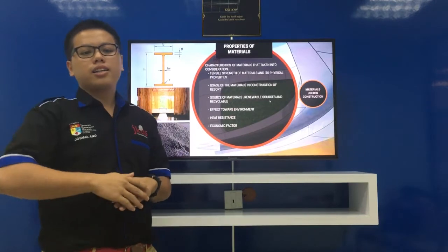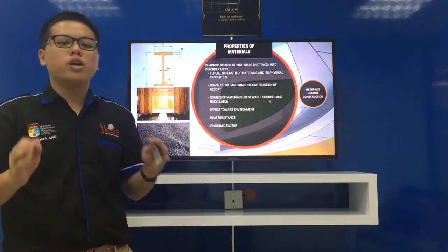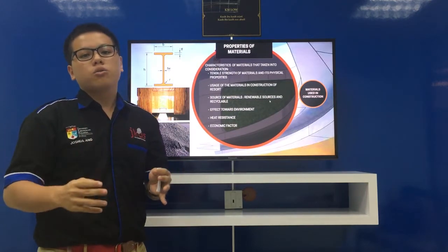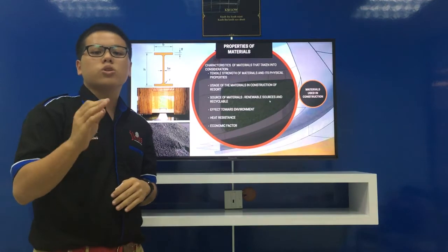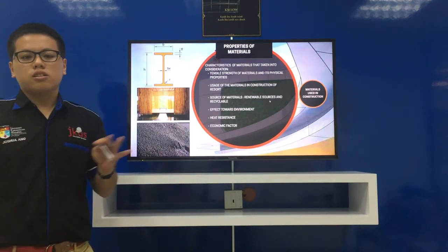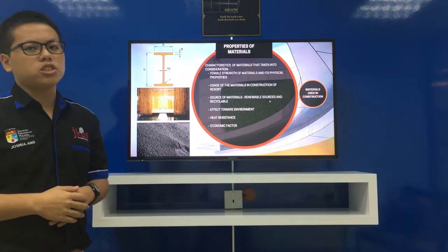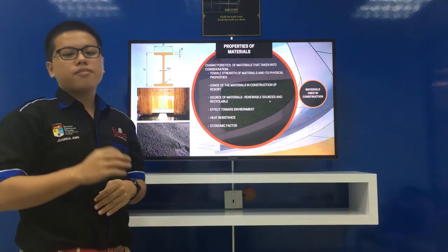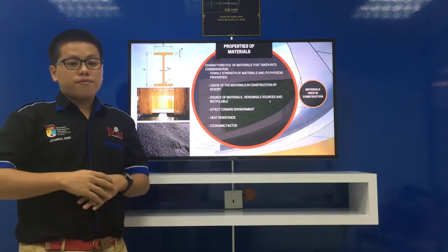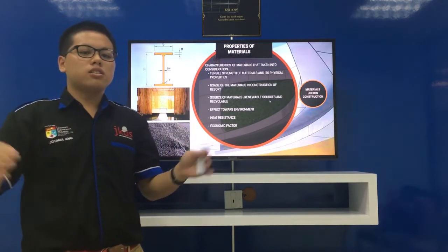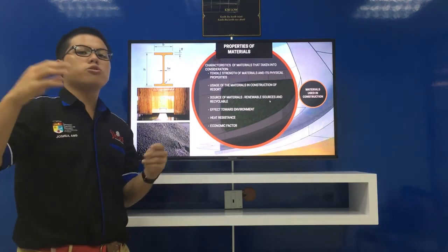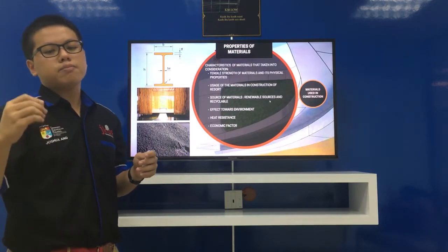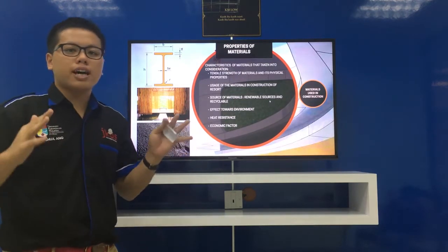Okay, in a beam under high stress, the axial fibers under the highest stress are the ones furthest away from the neutral axis. An ideal beam is one with the least cross-sectional area needed to achieve the section modulus. Since section modulus depends on moment of inertia, an effective beam must have most of the material furthest away from the neutral axis. Therefore, the further the material is from the neutral axis, the larger the section modulus, and it can resist a higher bending moment. Therefore, why do we choose I-beam?